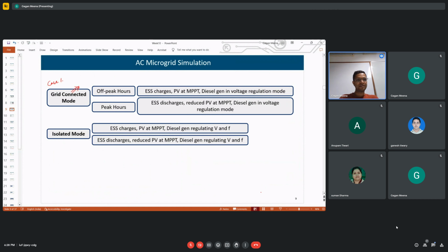In the second state, which is the dynamic state, the Q requirement is 40%. Hard limit means we have enforced that the Q requirement is exactly 40%. And then the third is the entire Q limit up to 100%, so full Q requirement is there. That is especially for fault, because during a fault the voltage suddenly dips to a very small value.